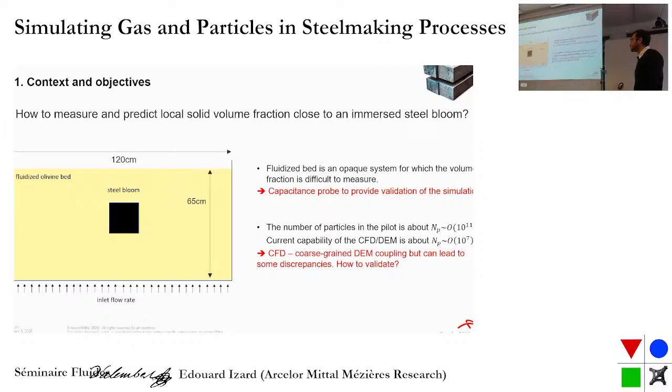different phenomena we can measure? So first, fluidized bed, it's a quite dense system, in fact, and optical measurements are quite complicated to perform. And also because you are completely immersed in this opaque system, we need to develop some strategy to measure the volume fraction. So what we developed is a capacitance instrument to measure solid volume fraction. So I will show you after the measurement we have done.